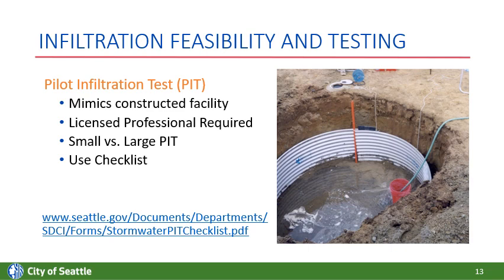And it's more complex. There's more excavation that's going to be required, and the intent of this test is to more closely mimic the actual finished condition of the facility. The test has to actually be conducted at the proposed bottom of the facility. So if, say, you're installing a 4-foot deep dry well, the simple infiltration test is only going to require you to do the test at 2 feet deep, but the pilot infiltration test, you have to conduct that at the proposed bottom of the facility.